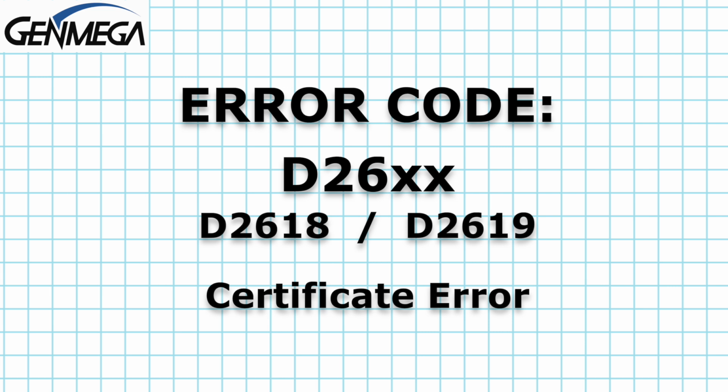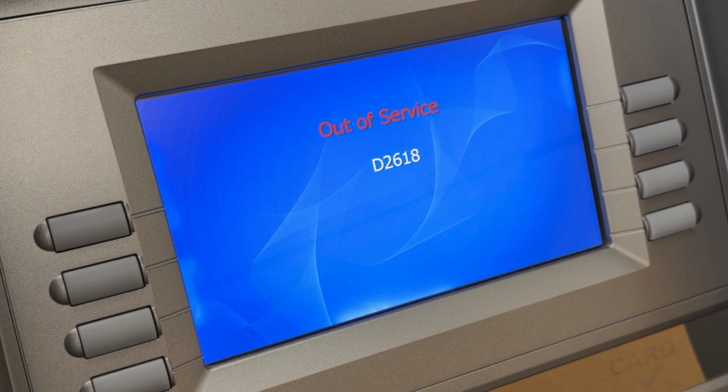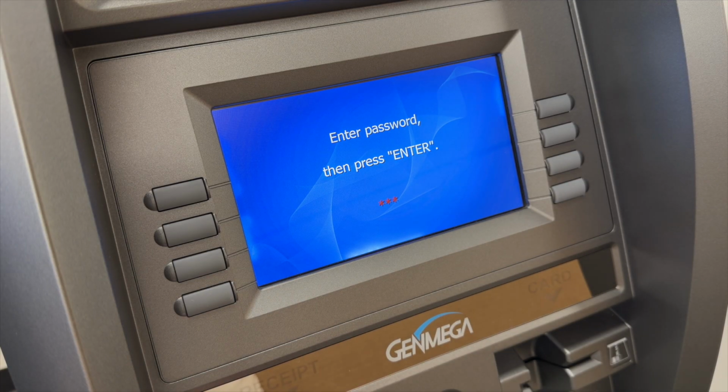part of the verification process to ensure that you're actually communicating with the host. So how do you troubleshoot this code? If you have an ATM that has been in service doing transactions and out of the blue it starts throwing this code, the most likely cause is that the date and time are off.